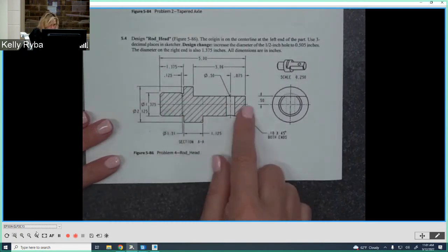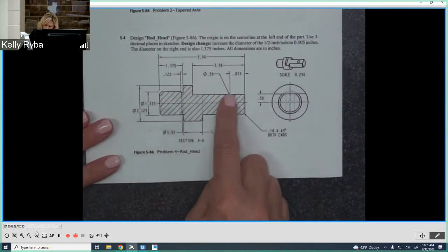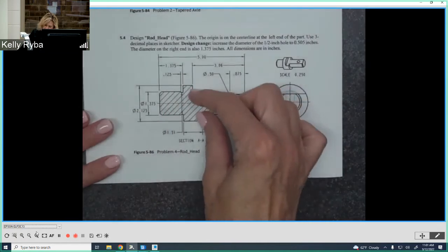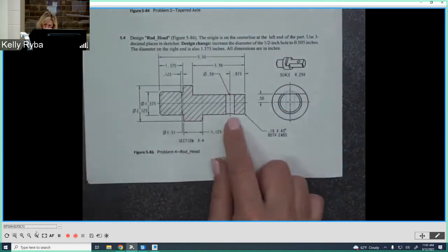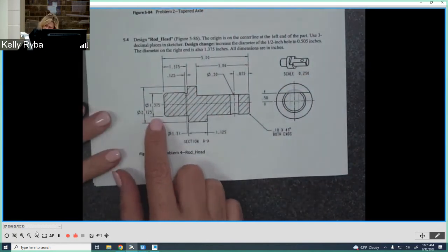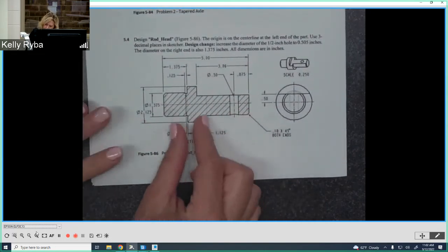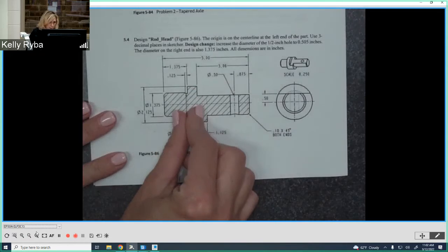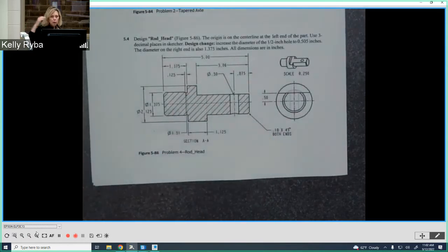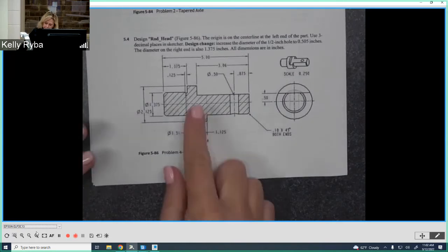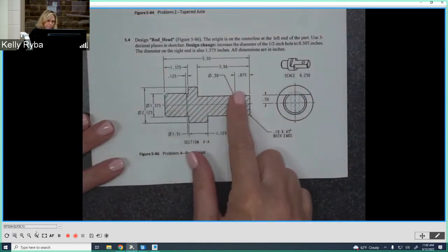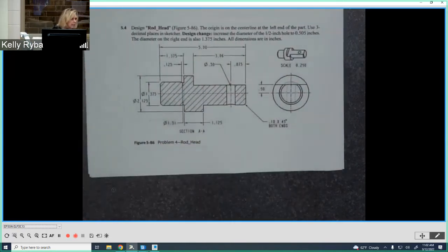I'm gonna revolve around. I'm gonna do the profile, okay? But I'm gonna make it solid and symmetrical just like we see here. So this 1 3/8 dimension is gonna be the full right side, okay? And then we're gonna have the collar as a full collar, all right? Because when we revolve, I wanna go around and have that full part, and then I'm gonna do an extrude to get rid of this part, okay? So let's set up that way.